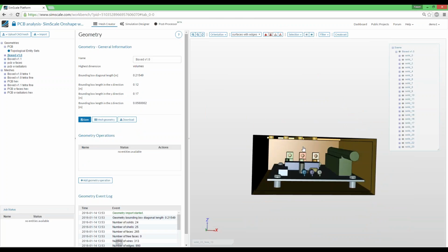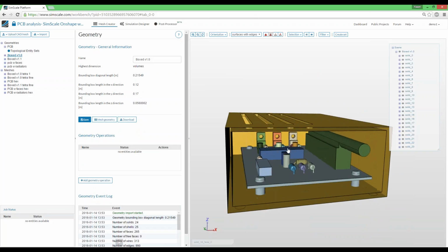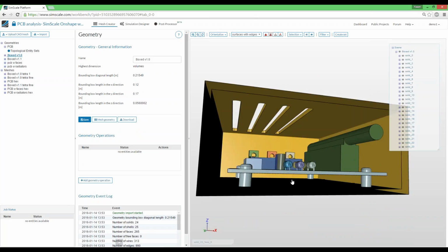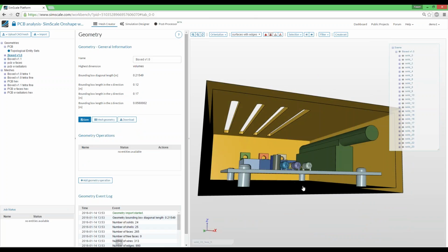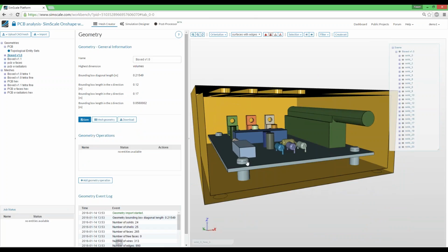So in this particular case, the only way for the heat that comes from, for example, the processors or resistors to be transferred through the solid bodies, without taking into consideration the gas around it, it would have to go through the whole PCB board and through those little legs over here and then be transferred here.